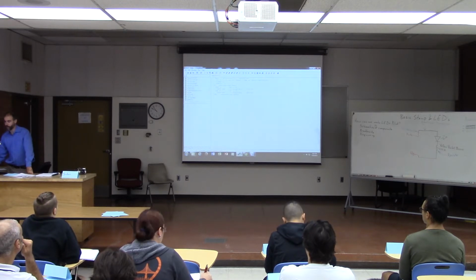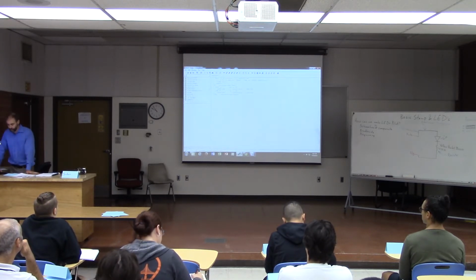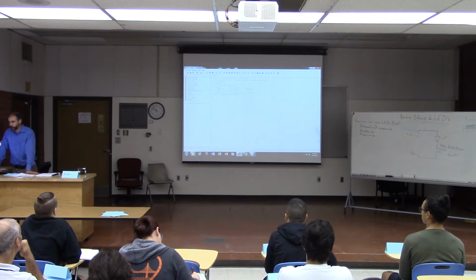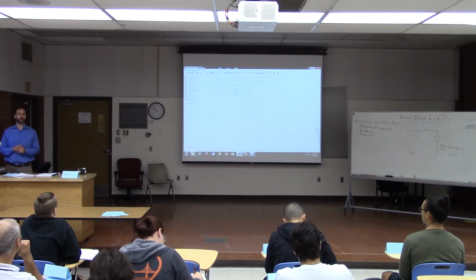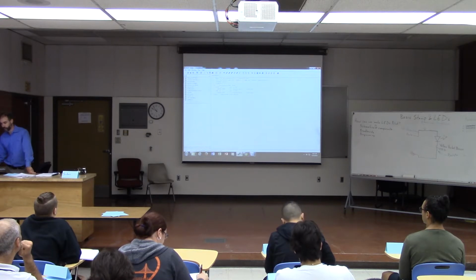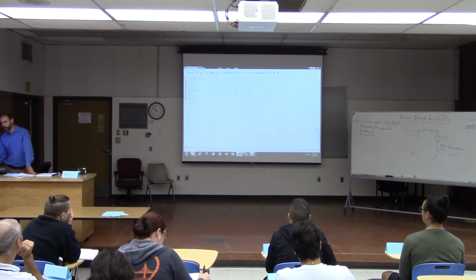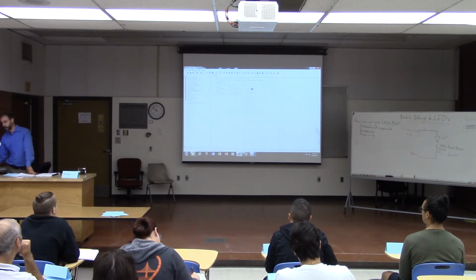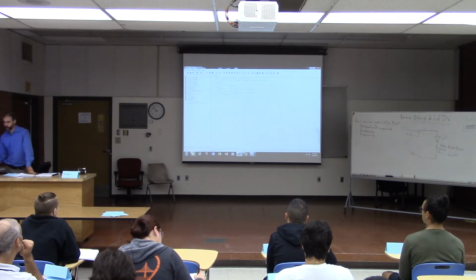Anything in green is called a comment. That's something that doesn't actually affect the program, but it's a note to you to remind you of what's going on. So this says when we have pause 500, that's a 1/2 second delay. Okay? So pause 500 means we're going to wait for 1/2 second.